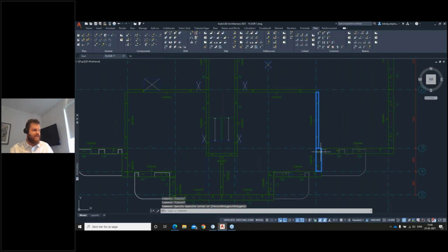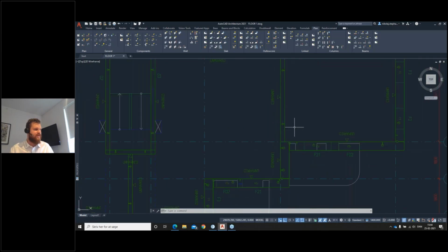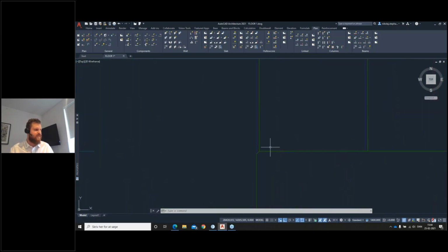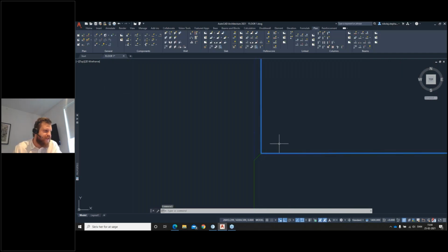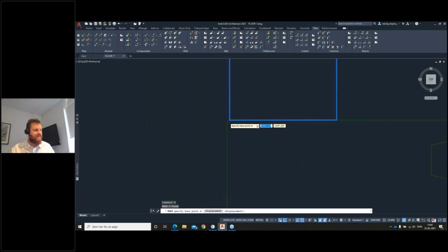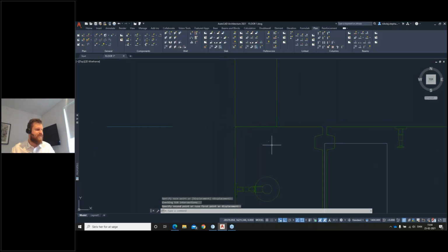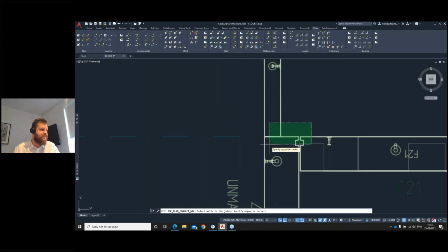So let's just get back to that here. It doesn't show the exact correct one I want to use. And now you can see why when I zoom in here. Can you see that? Because I snapped wrong in my AutoCAD. So I was just talking about the snapping. This doesn't want to connect the wall into the middle of the other wall. It has like a rule for, of course, you need some rules to be able to do these connections here.